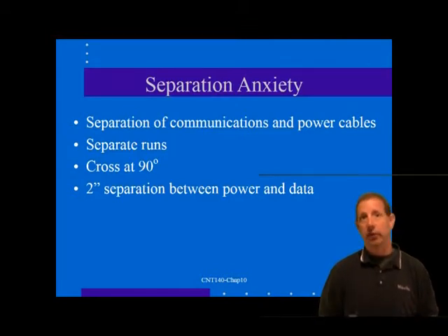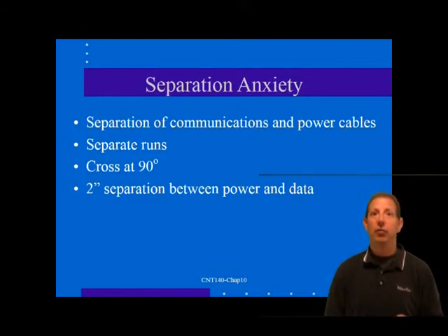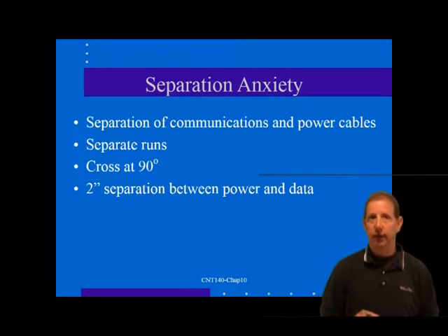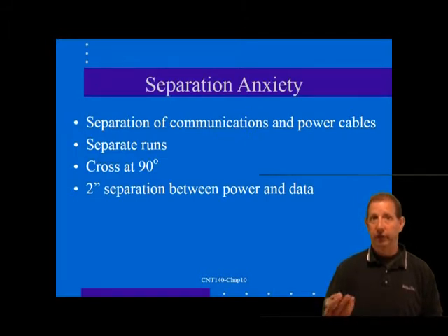The safety issue is a little more ominous. Electrical codes, such as the NEC, forbid placing power conductors and communication cables in the same raceway. Power conductors are considered Class 1 circuits and are expected to have hazardous voltages and the ability to deliver dangerous levels of current. Communication cables, on the other hand, are Class 2 circuits as defined by the NEC, Article 800 communication circuits.